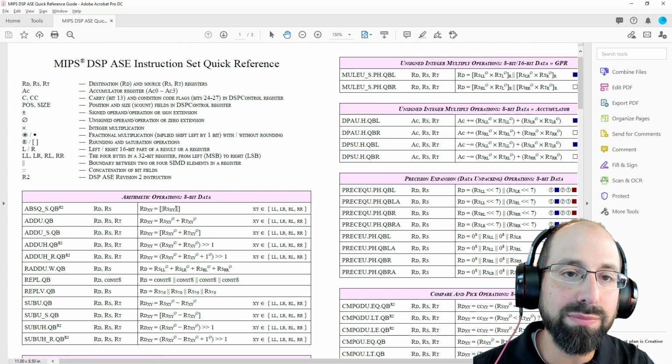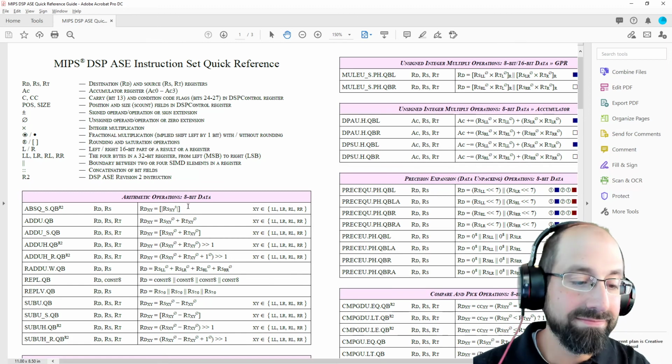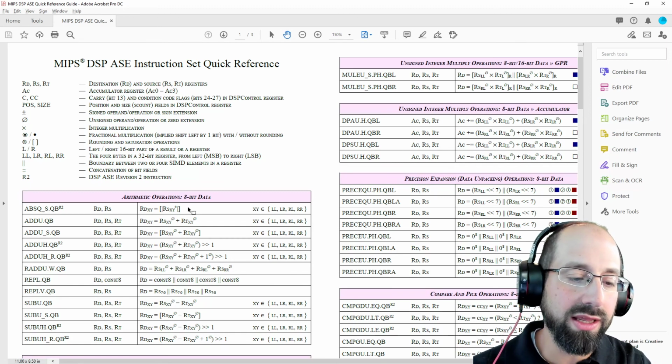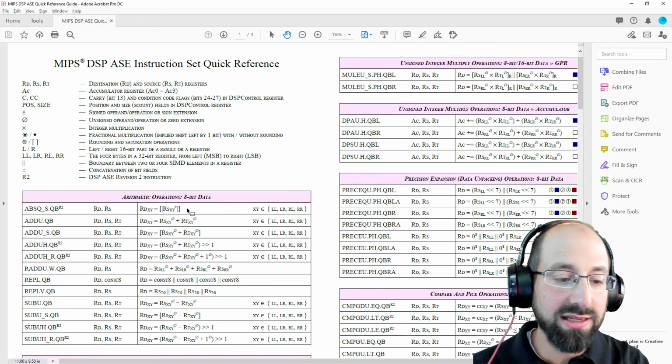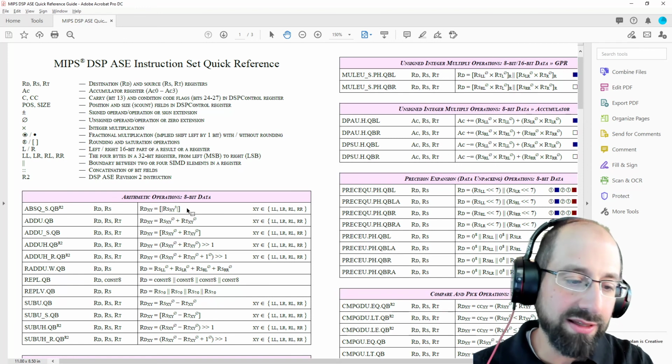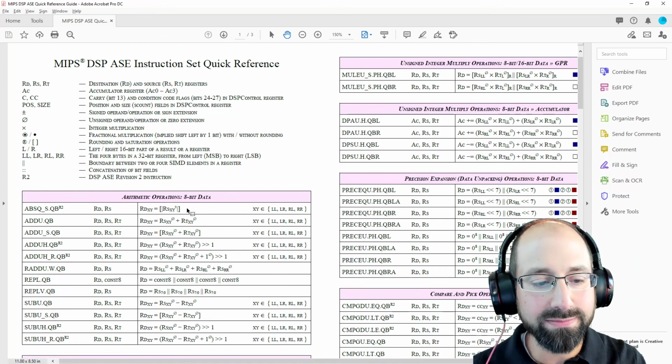This is taking our input on a byte by byte level, and it's checking the sign bit. So that would be a pretty easy operation, right? Whether that needs to engage the ALU or not is like what we were talking about for the replicate instruction. Check that sign bit. If it is 1, convert it to the 2's complement of that value and store that as my output.